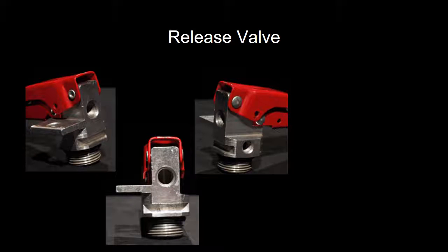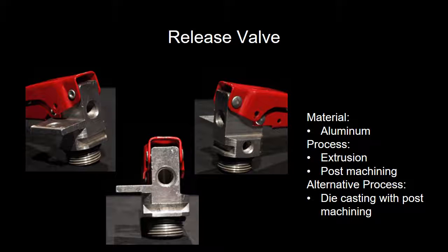The release valve is aluminum and appears to be an extrusion with post-machining processes. This method was determined given the difference in surface finish from the sides and the face. Using extrusion would reduce the amount of material required and machine time necessary. After cutting the extrusion to length, the bores and external features are machined. Alternatively, the part could be die-cast and post-machined.